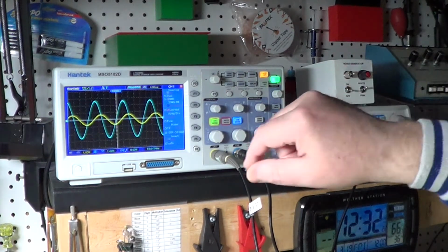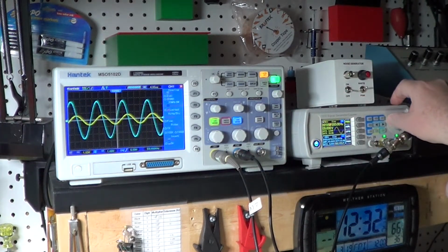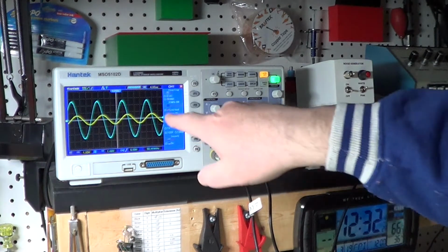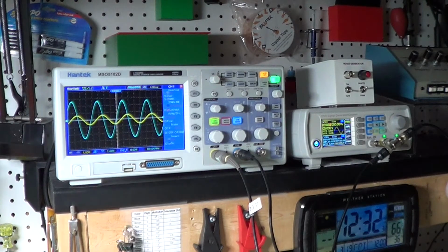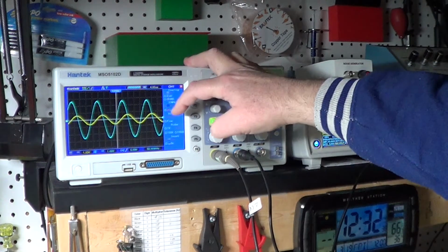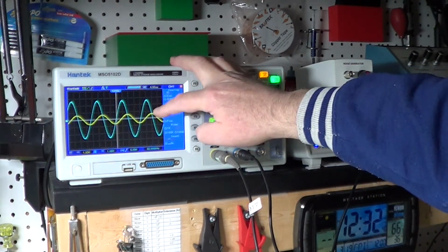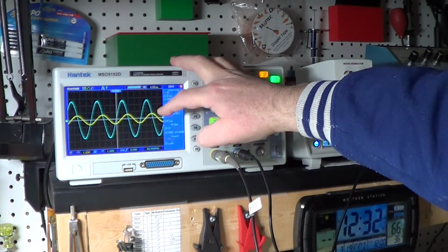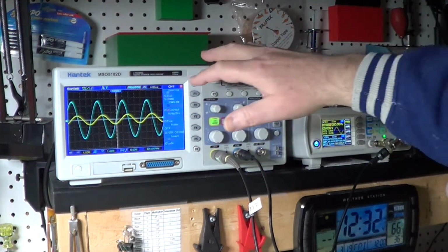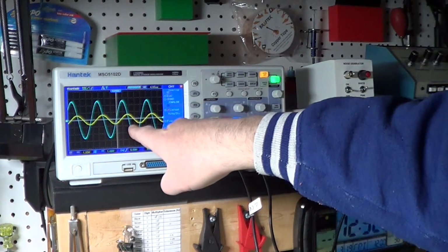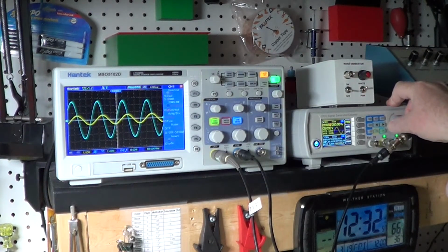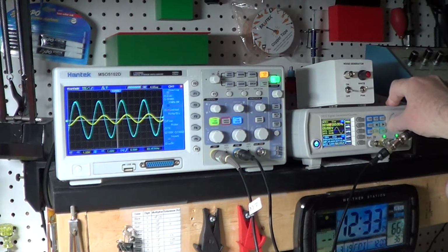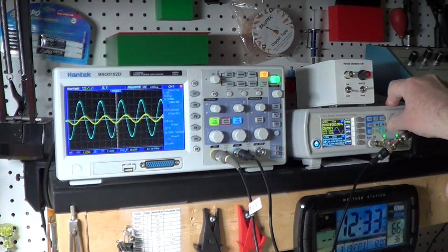Now let's go to 60 kHz here. Look at this now. The output is very low, so we have almost eliminated the signal from the output. Now it's below 2 volts, it's about 1 point something volts. And look at the shift, it's about 90 degrees now. And the output anticipates the input. So you can see this is the effect that a low pass filter has on a wave.